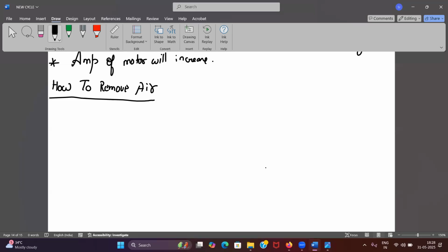So let us discuss how you will remove the air. Tell me, someone, what you are going to do. Someone must know. Sir, may I? Sir, firstly, first we have to pump down the compressor. Excellent. We have to close this. First step is pump down.